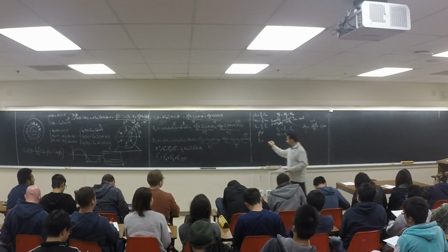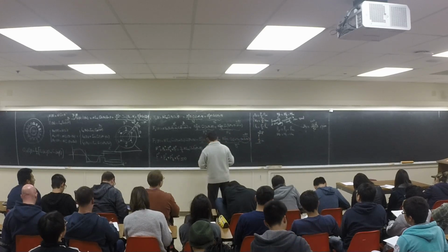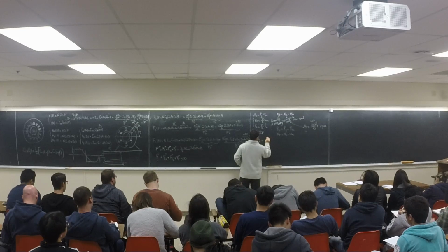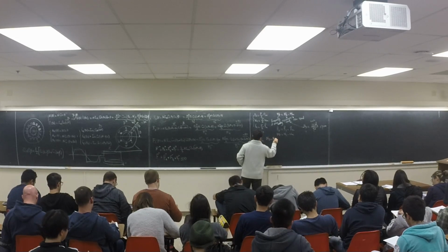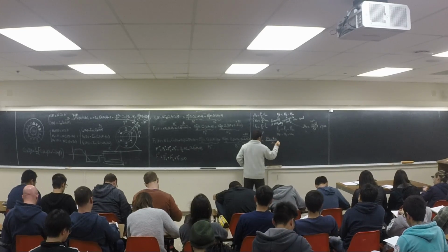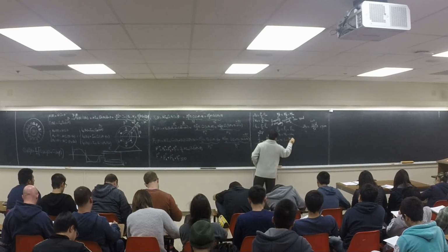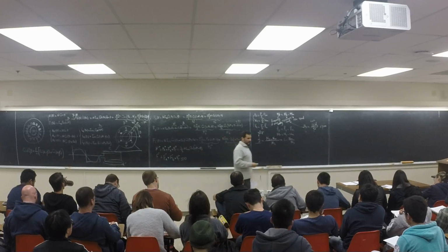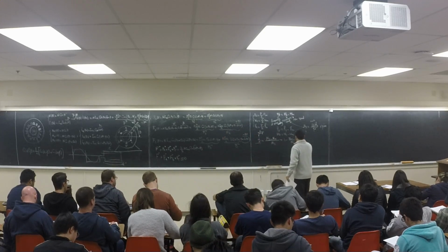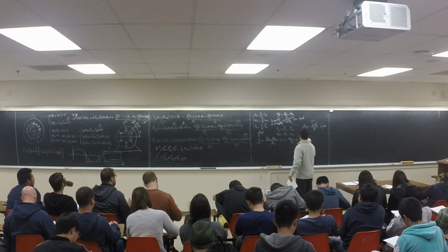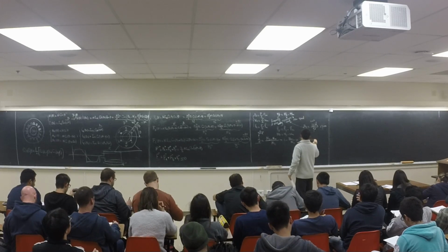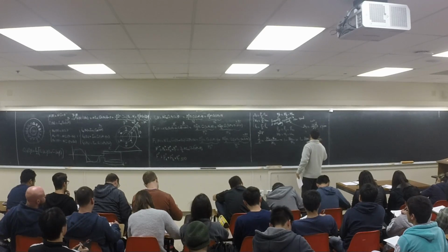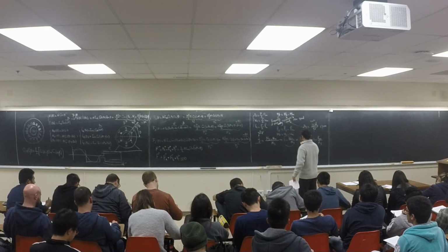Now, slip they define it as Ns minus Nm over Ns. Or it's going to be 1 minus Nm over Ns. Or you can say 1 minus omega m over omega s. Or you can say 1 minus Fm over Fs. But these two are more common equations.